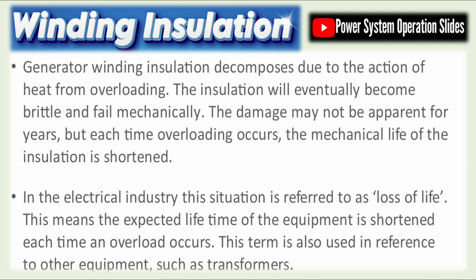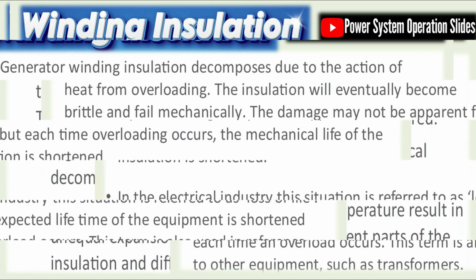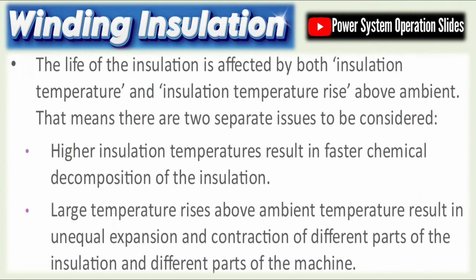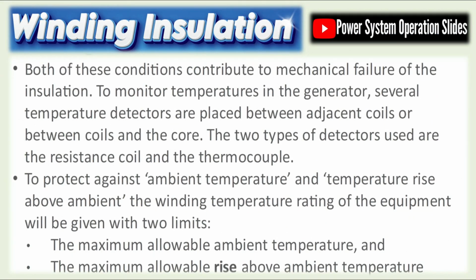Fossil fuel power generation. Coal power generation involves complex processes: fuel handling, combustion, flue gas treatment, ash handling, and waste heat recovery. Supercritical and ultra-supercritical boilers operate at high pressure and temperature for better efficiency. Natural gas plants are favored for their flexibility and reduced emissions. In open-cycle gas turbines, the thermal efficiency is lower, around 35%, but in combined cycle operations, it can exceed 60%.